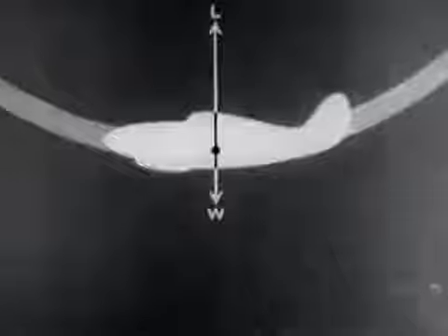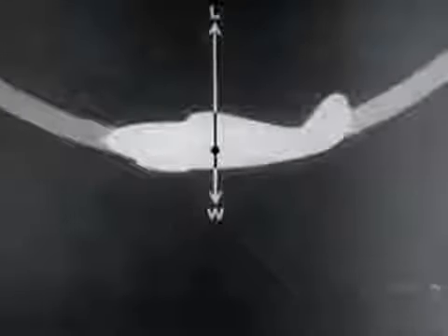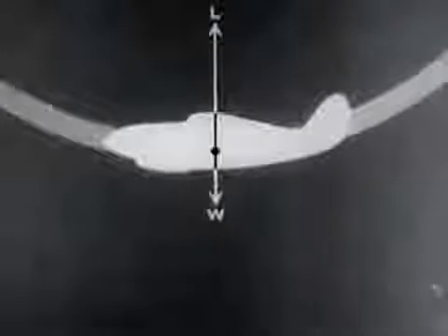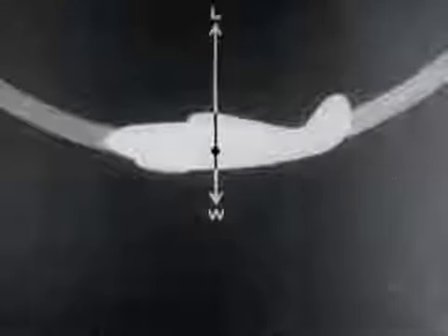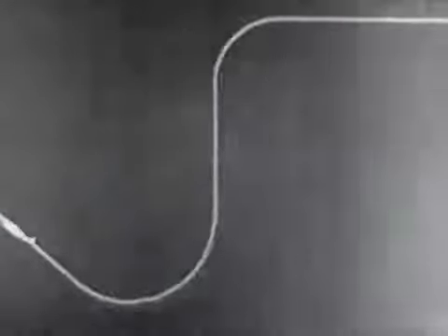In pulling out of the dive, the angle of attack must be increased slowly. During this maneuver, lift may attain several times the value of the weight. This increase in lift produces acceleration, which in turn produces a curved flight path.